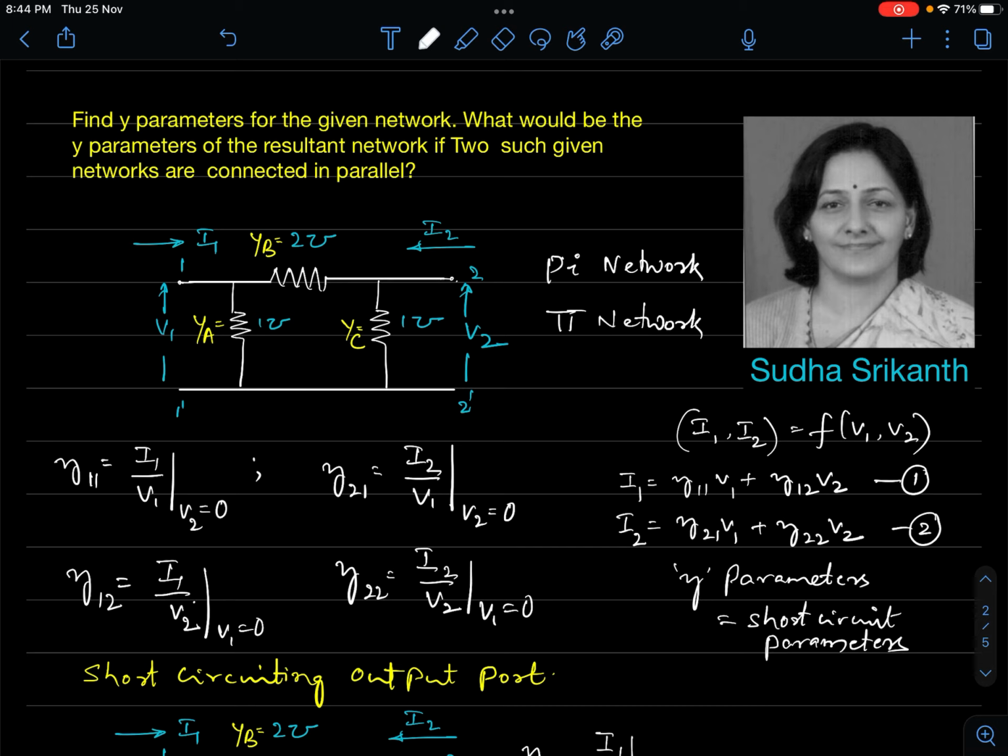Similarly, for impedance parameters, a T-shaped network is comfortable. From the star-delta transformation, it is possible for us to convert one shape into another. A pi shape can be converted into a T shape because the pi shape essentially is a delta connection, so it can be converted to star.